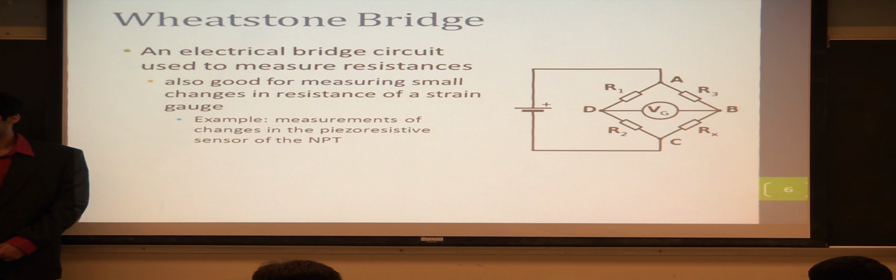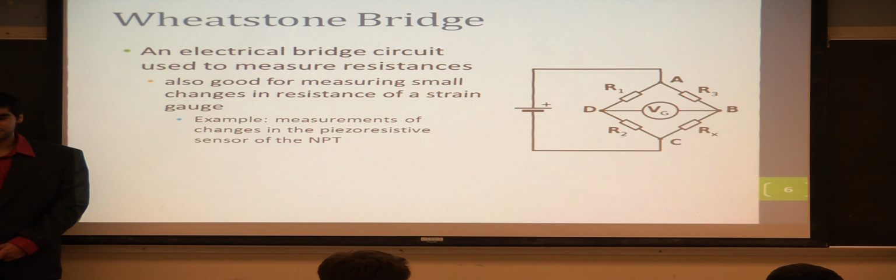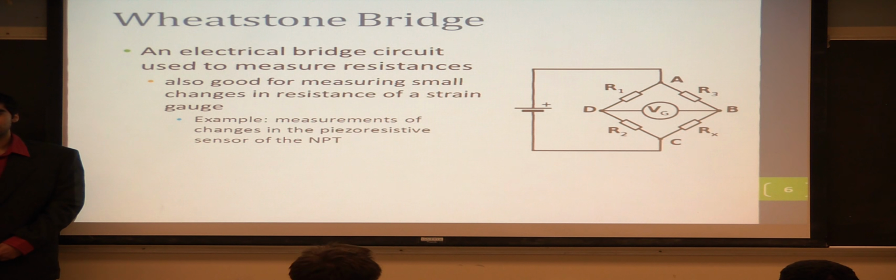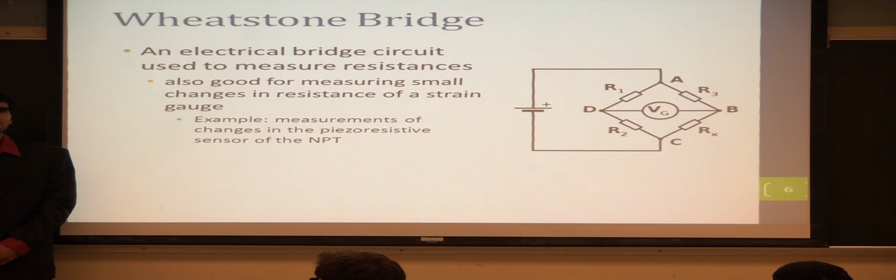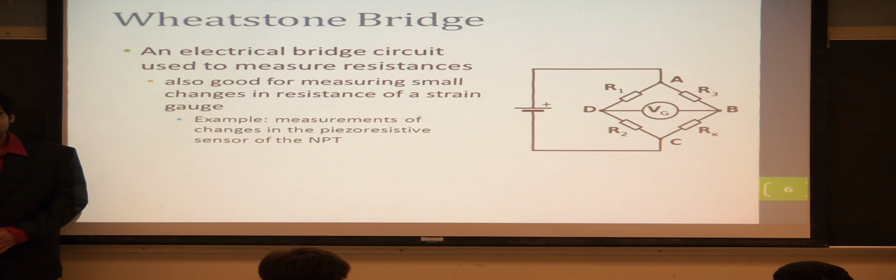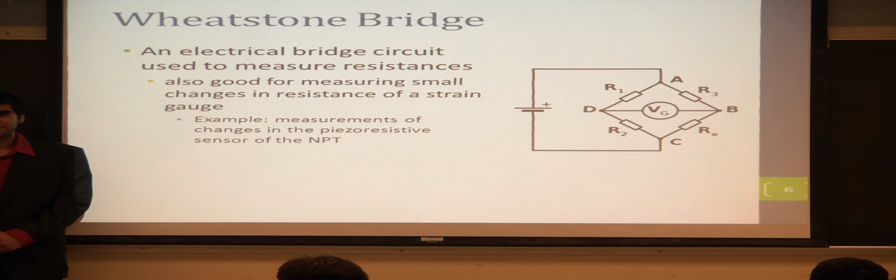And we have the Wheatstone bridge, which is used to sense small changes in resistances. In our case, when pressure is applied on the sensor and the pressure is sensed, there is less current passing through. And when the Wheatstone bridge can sense that there's a higher resistance and less current, then it will report that change as a pressure change when it's incorporated into our device.